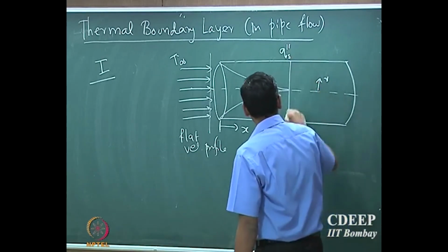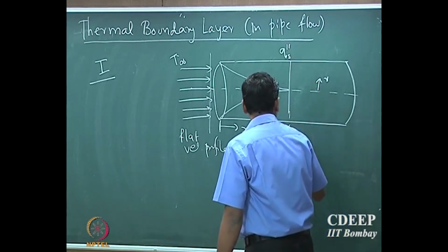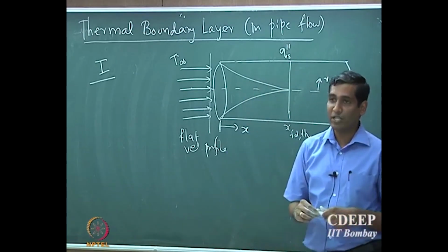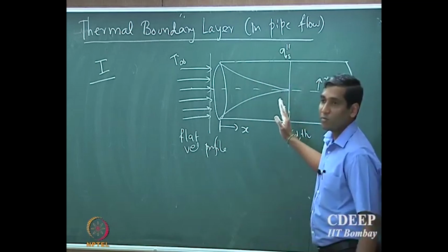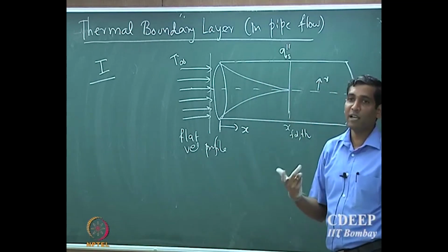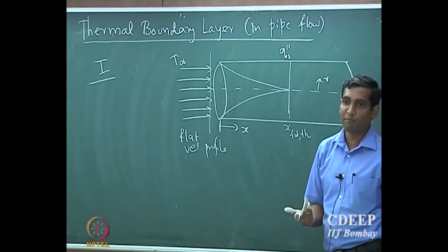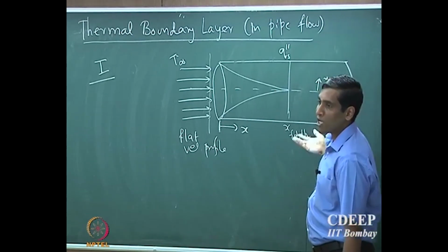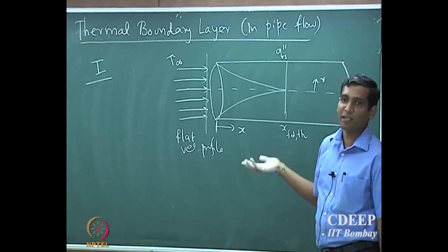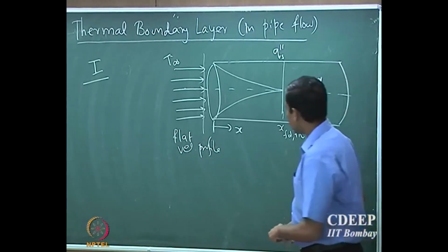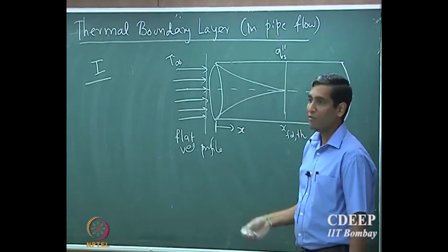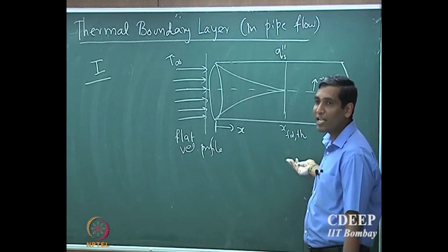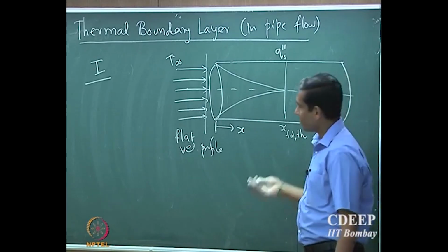That location is called the thermal fully developed region. At that location, every fluid particle in the cross section will now experience the presence of heat transport from the wall to the fluid, or vice versa if the temperature of the fluid is hotter than the surroundings. Okay. So now similar to the momentum boundary layer, we can define a thermal boundary layer and also a regime for fully developed thermal boundary layer condition.